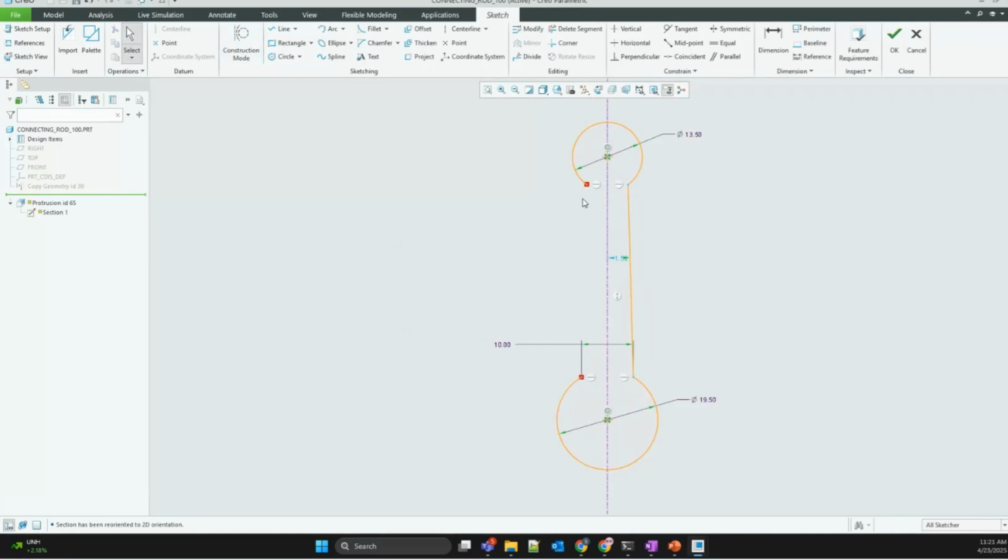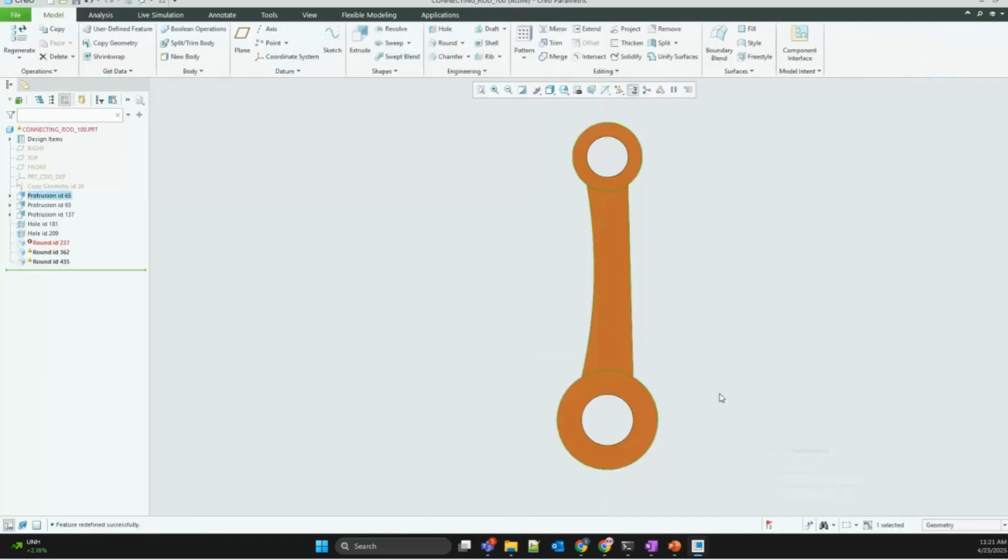And you'll notice, by the way, Creo warned me before I hit delete. It said, "Hey, hold on, something else is referencing this entity. Are you sure you want to delete that?" And I said, "Okay." I click delete. And now I'm going to go ahead and sketch my arc in this case. Here, kind of curve like that. I'll leave this as is for right now, and I'll hit OK, right?